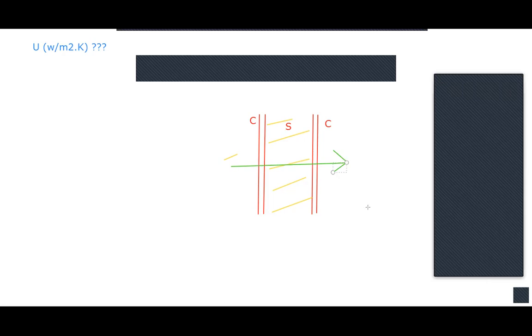So it is a linear heat transfer, I mean conductivity in solids, and one dimensional for simplicity. This is only a calculation at one point, one line going through a wall. It's a linear thing. This we can see also in the coefficient lambda, which has units of watts per meter times Kelvin. It's only a meter here, so it's linear.